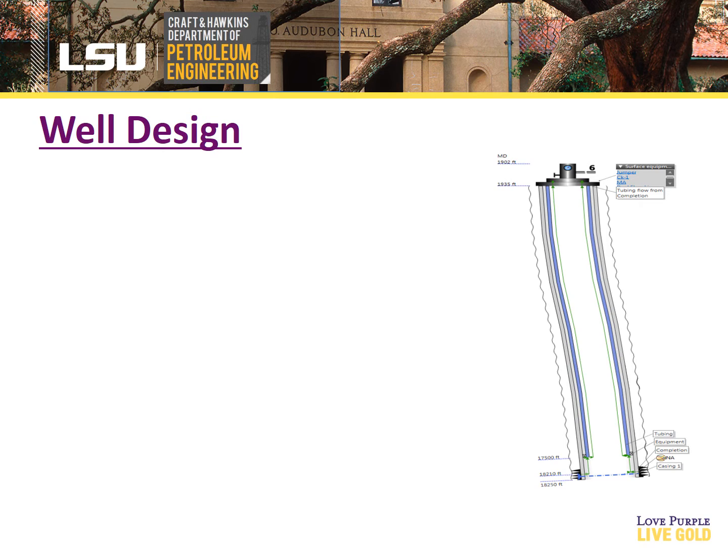As students, we were faced with the challenge of simulating the conditions previously described. We had the option of either using a VBA code in Excel or learning how to use PipeSim. Our team decided to use PipeSim due to the ease of varying parameters and visualizing these changes. PipeSim is broken up into two major components, the well and the network. We started with the well component, which constructs your production system from the reservoir to the wellhead.